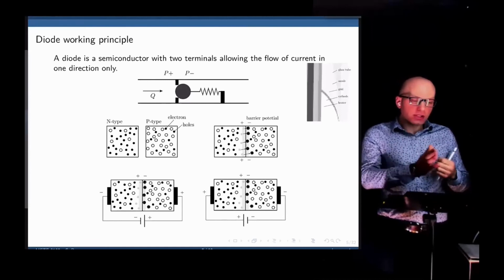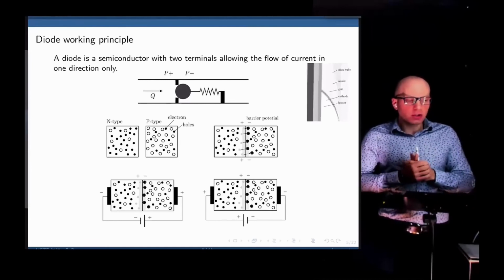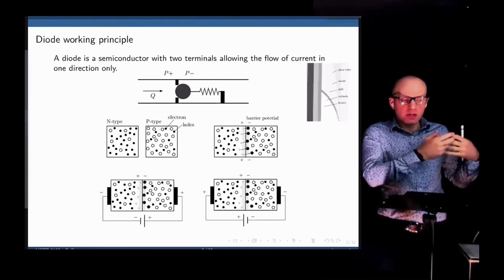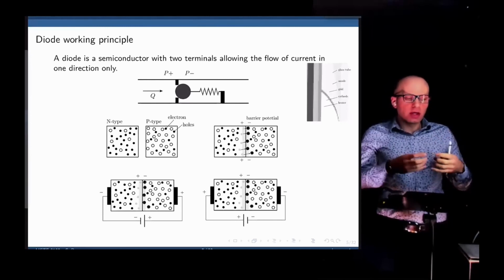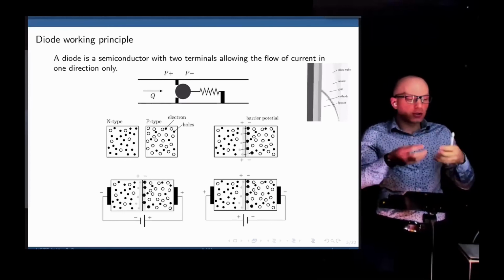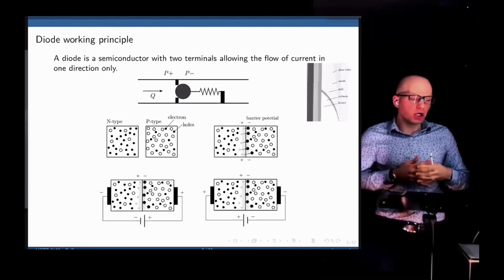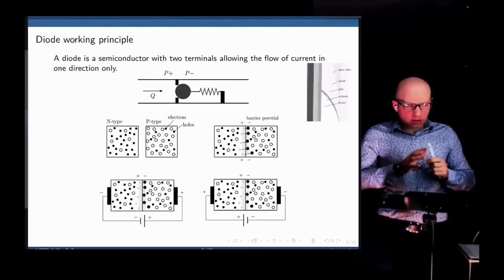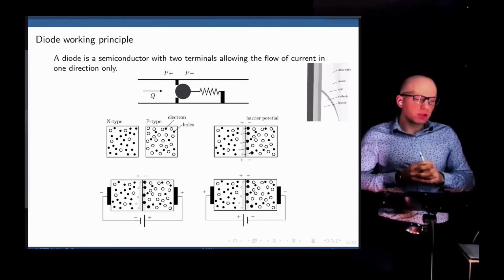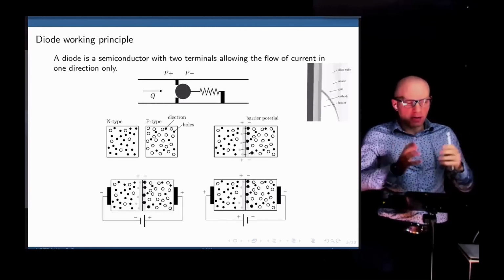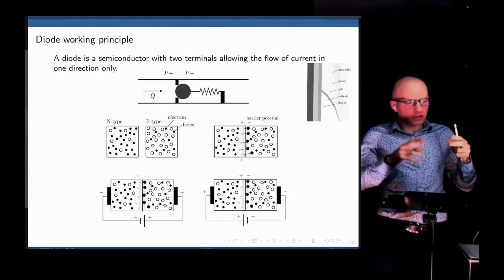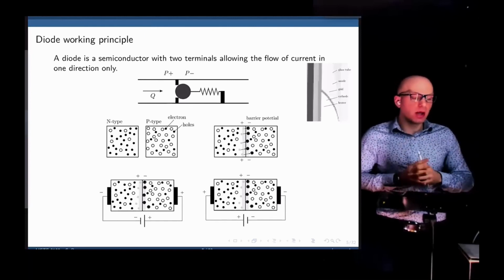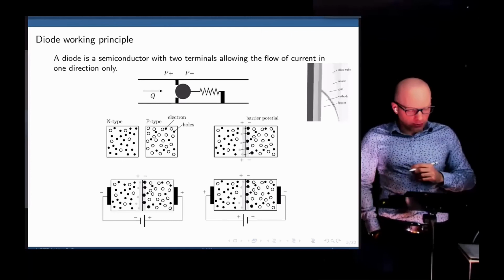On the P-type, we are going to add some impurities to that material that would otherwise be neutrally charged to create holes, to remove some electrons from that neutral charge, which will create a positively charged side. These diodes typically use silicon as the main material, and another material is added to create these holes or to inject additional electrons in the material itself.